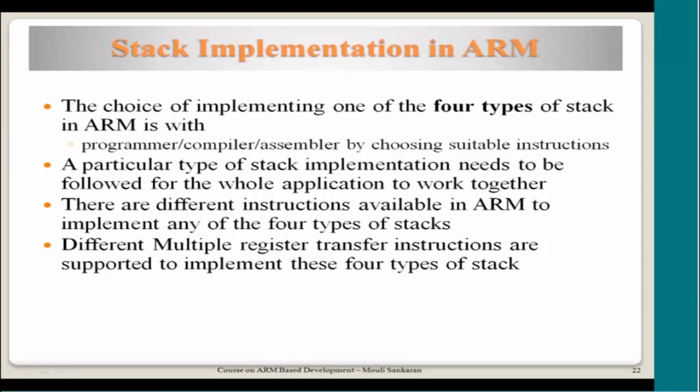Then what you push, you may not be getting it from the start. So the flexibility is there, but needs to be taken with a pinch of salt, and we need to make sure that the writer, especially if you are writing assembly code, remembers to use proper code for both pushing and popping the values into the stack and taking the data from there.